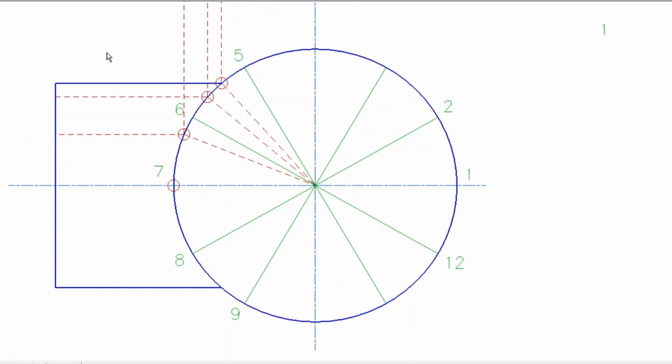So what you're going to do in the exam is measure the distance, let's say from 5, with your ruler. Obviously this is a curve, so technically that's not correct. But if you measure the distance from 5 to 6, or let's call this 5A and that 5B, from 5A to 5B you can measure that distance with the ruler. Then from B to C you can measure the distance with the ruler, and then from C, if this is 6, you can measure the distance to 6B and then to 7. You can take those measurements and plot them on your development.